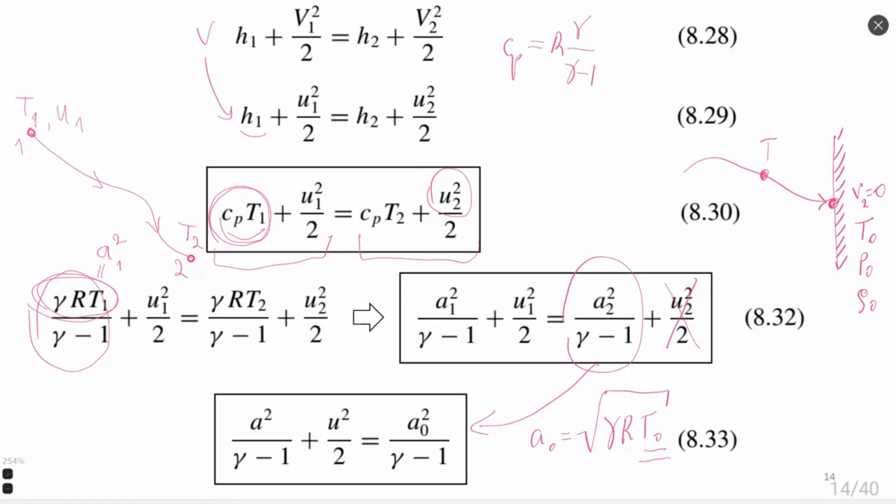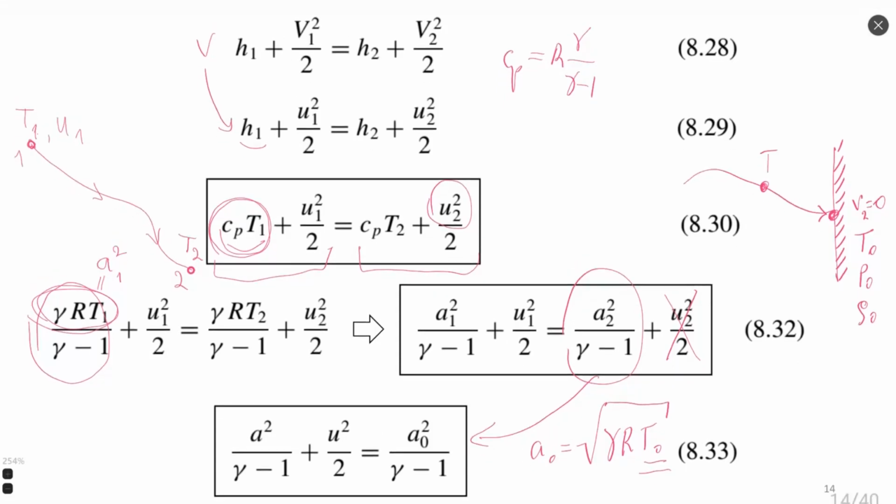And then you obtain speed of sound. This is valid for any particular point in the flow, and also valid for stagnation properties, when flow is stopped until 0. So stagnation speed of sound. Equation 33 shows to us this relation, this form of energy equation.